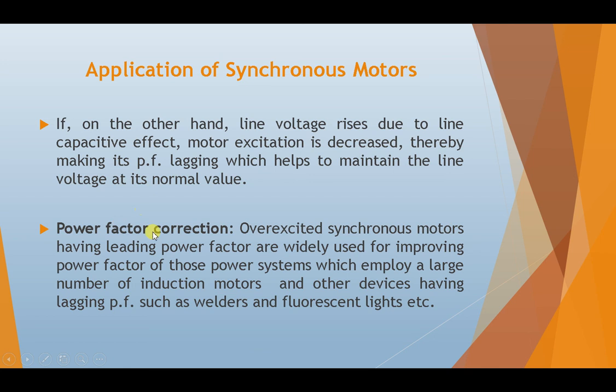The next one is power factor correction. We studied this in the synchronous condenser. Over-excited synchronous motors having leading power factor are widely used for improving the power factor of those power systems which employ a large number of induction motors and other devices having lagging power factor.